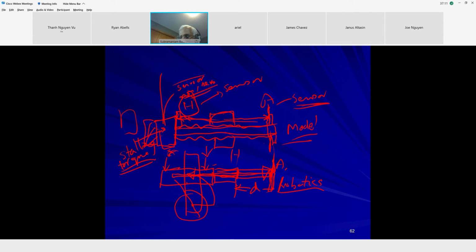Now, is it open loop or closed loop? Well, depending on how you define open loop and closed loop, it could be called a closed loop, but with very limited capability. I cannot control any of the intermediate positions with this method, with only two sensors. Now, can I put a sensor which is going to continuously tell me where the load is? Yes, it then becomes a servo. That means you are putting in position feedback. Okay, not so with the air cylinder.